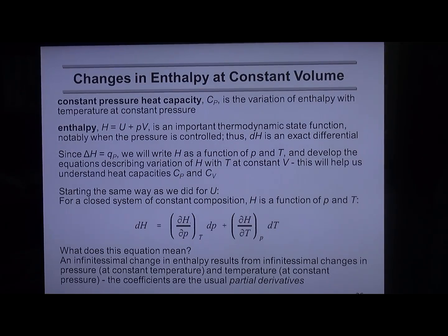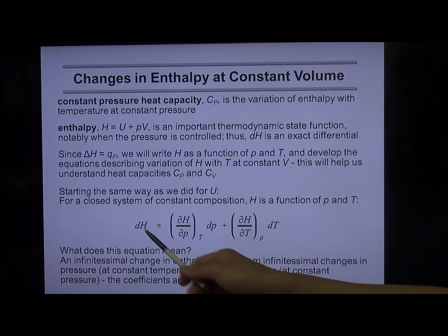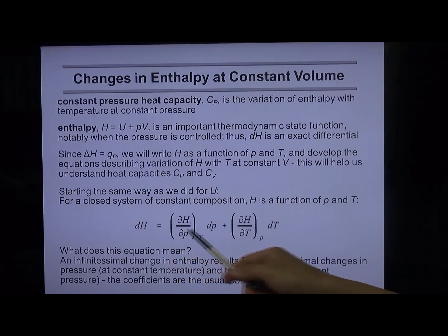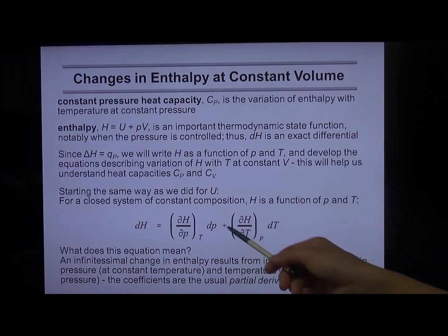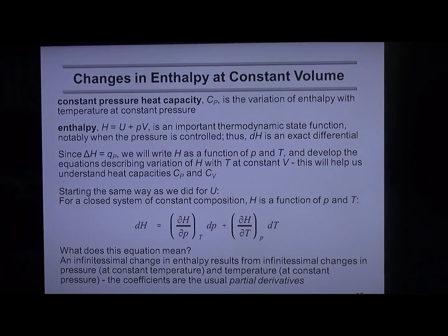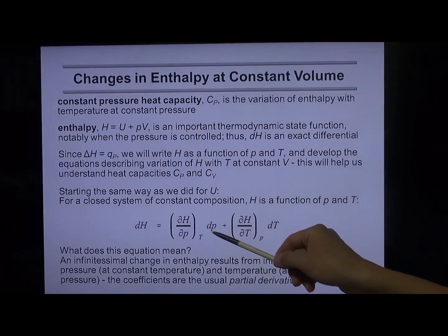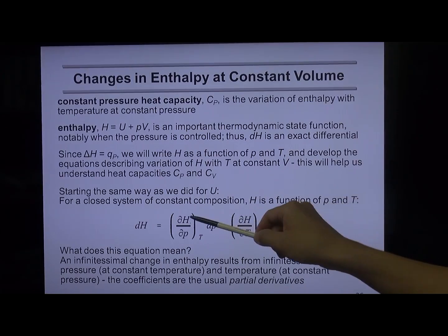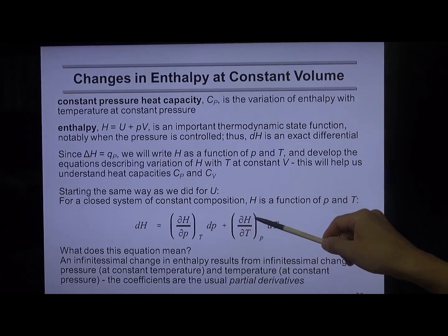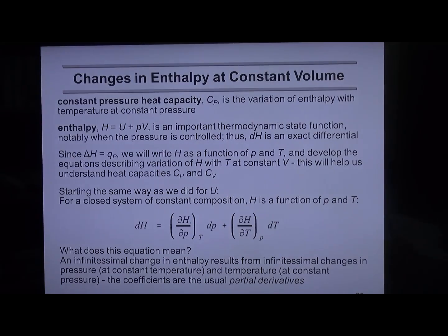How about enthalpy? We went through the interesting processes for internal energy. We do the same thing for enthalpy. Express enthalpy as a function of pressure and temperature. Not volume and temperature this time, pressure and temperature. Okay? Then enthalpy changes as a function of pressure this much, and as a function of temperature this much: round H round P at constant temperature, round H round T at constant pressure.